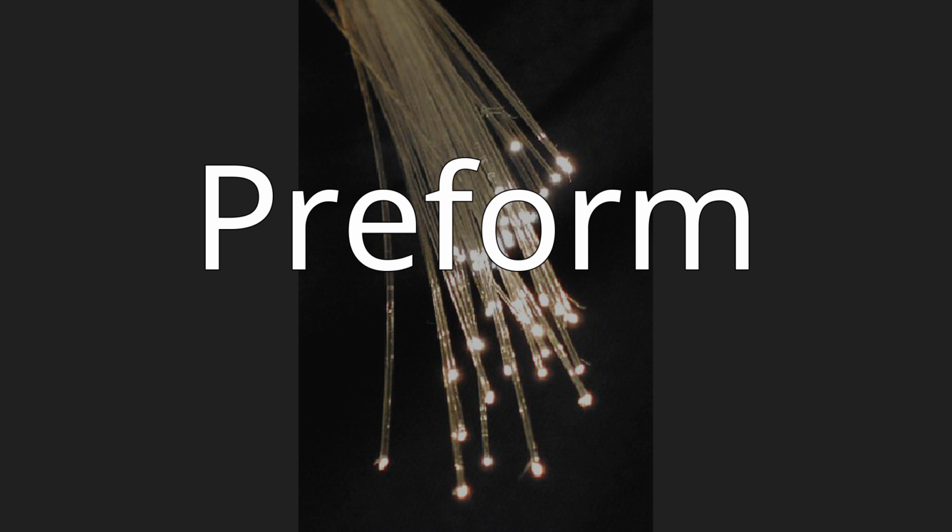Nevertheless, careful polishing of the preform is important, since any defects of the preform surface affect the optical and mechanical properties of the resulting fiber. In particular, the preform for the test fiber shown in the figure was not polished well, and cracks are seen with the confocal optical microscope.